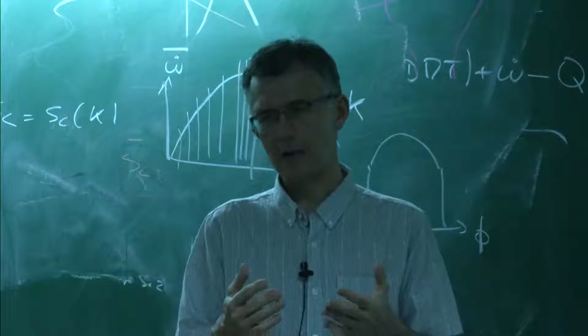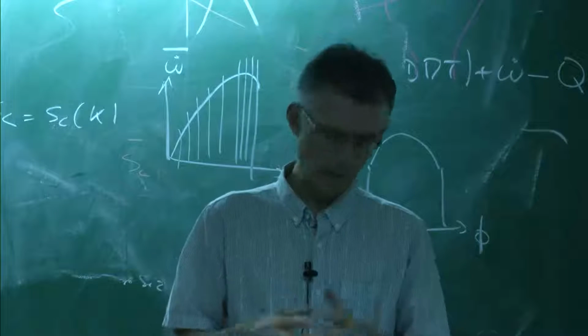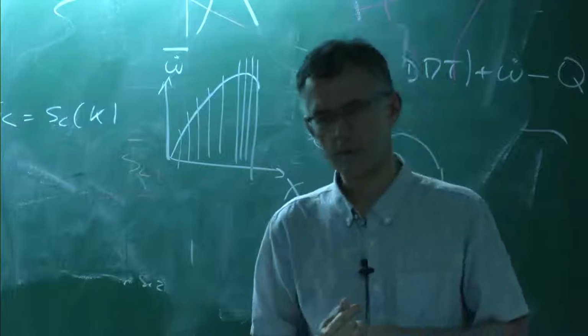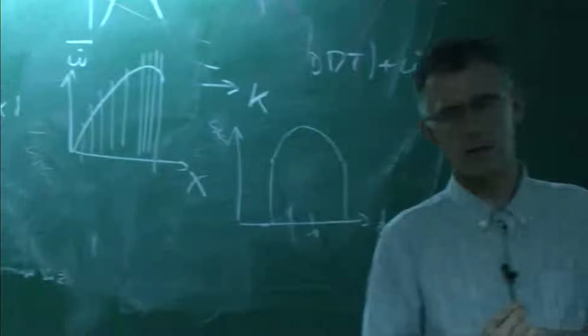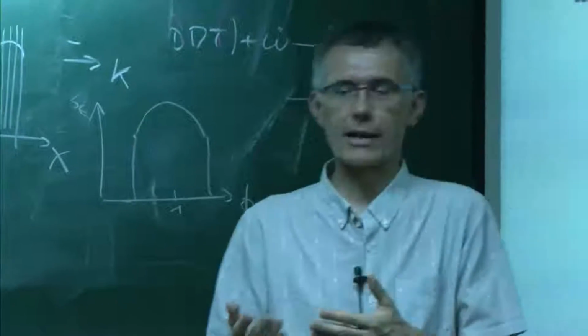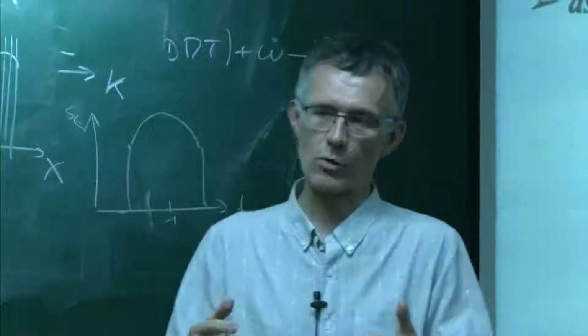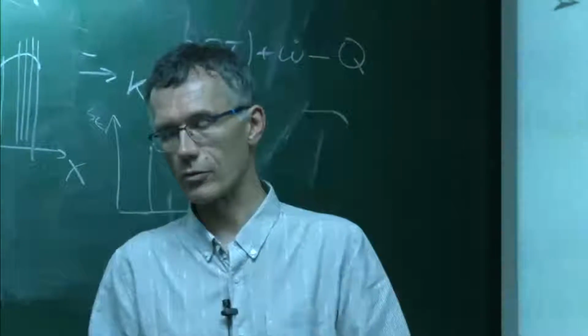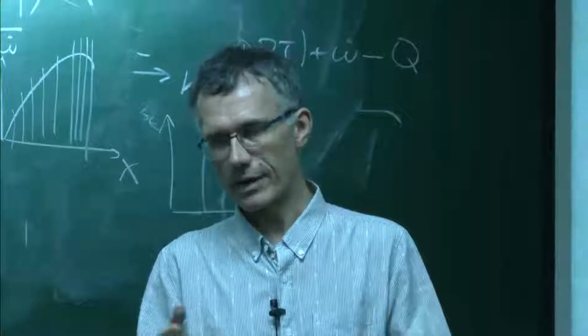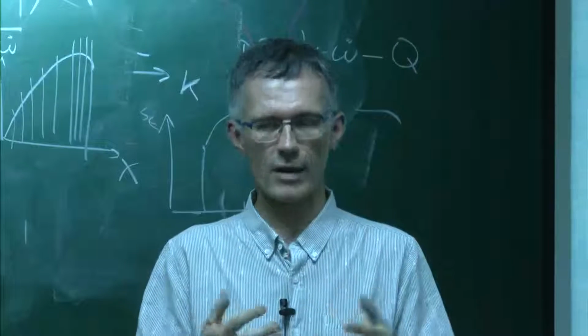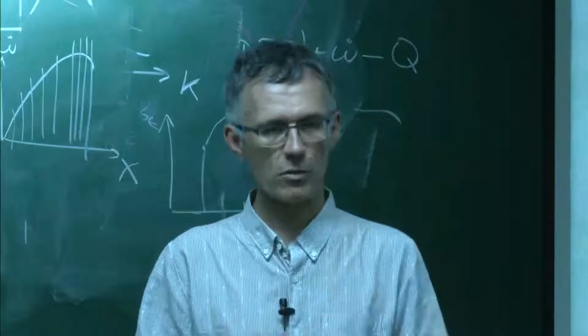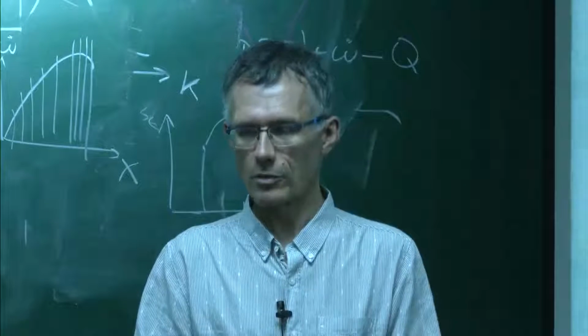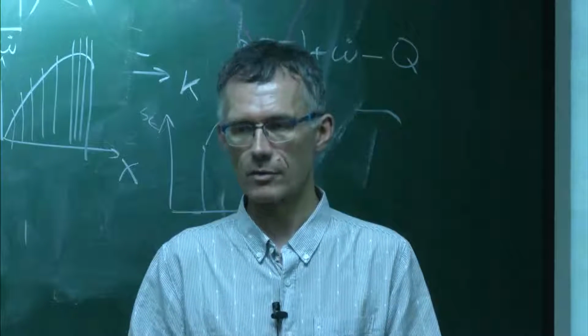What about near-wall treatment, for example? Yeah, and at the wall we use the law of the wall. The law of the wall is a little bit like a hybrid method, except you do LES everywhere, and at the wall you use the law of the wall. Around an aircraft, I think DES is much more adapted, but in a combustion chamber, we don't use it. I know that some codes can do that, using DES.